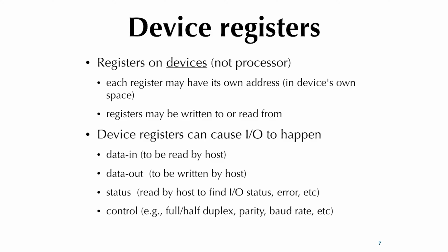And same thing with the little SD card. How do you access an SD card? Well, you form these commands to access the registers too. So a lot of times there are these command formats, and the SD card has either what's called SPI compatibility mode, or 4-bit data and then a few other control bits. Whichever way, there's a format you have to follow, and then read and write accordingly.